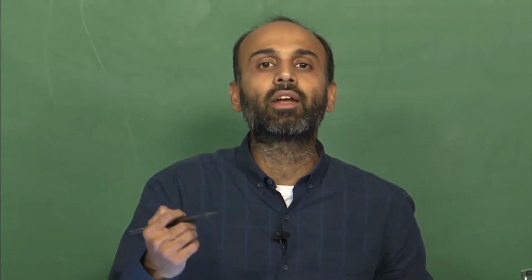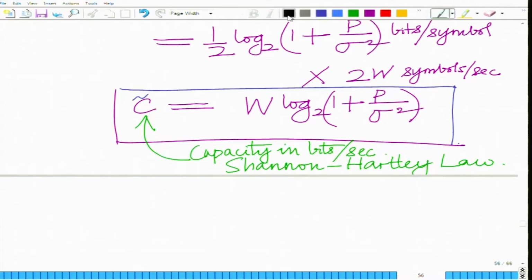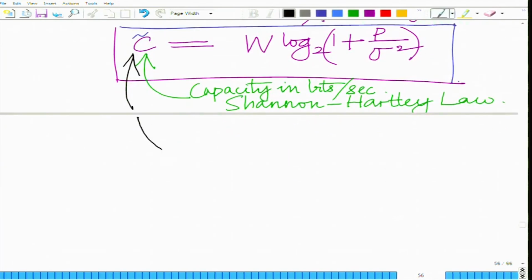Shannon's work is much more general and provides a framework to characterize the capacity of any channel. This particular result is for the Gaussian channel, and it is fundamental in its own right, because the Gaussian channel is one of the most frequently occurring and popular channel models, and widely applicable in practice. It is a very elegant and simple result.